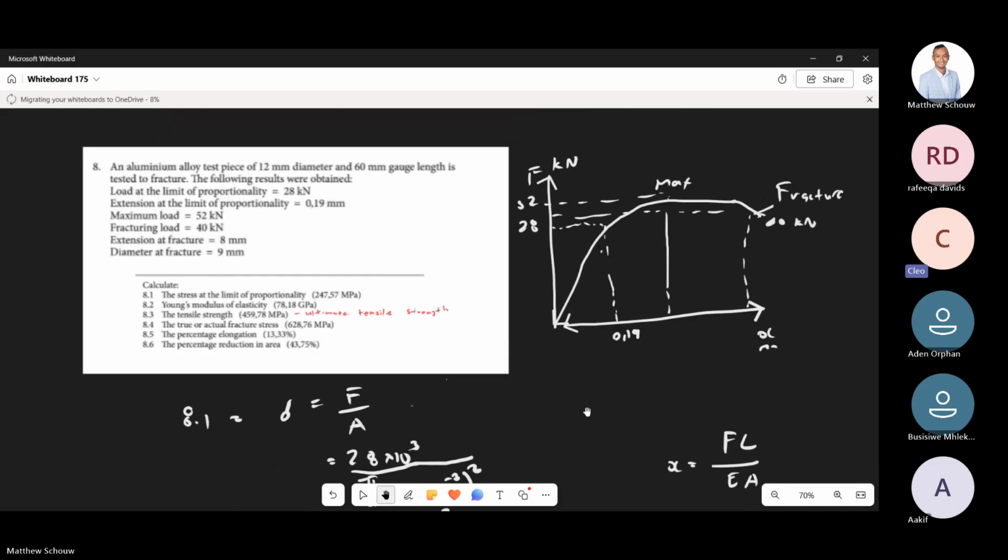So with regards to the nature of that force, when you write down the answer in MPa, will you say that it's tensile or negative or positive? Because we're doing a tensile test, we don't have to worry about that now. That becomes more predominant in the temperature stress part. But you can write plus. Plus means tensile, negative means compressive. But it's a tensile test, you know what I mean? That's a very good point though. Okay, let's quickly work that out. You should get that answer.